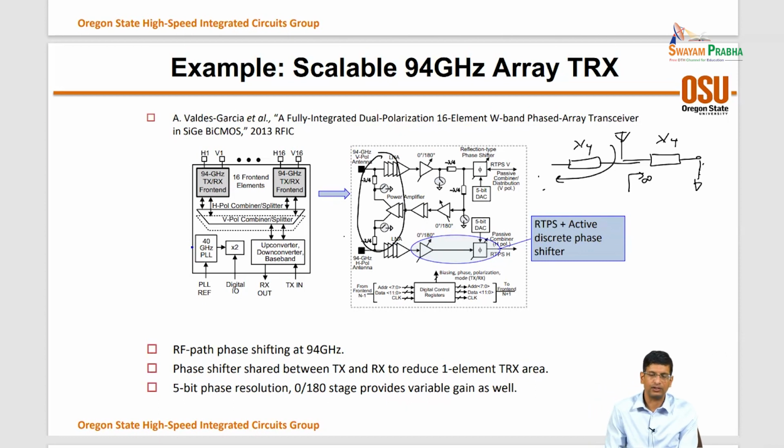And what you can actually do is start integrating some of these things inside the design itself. So in here, for example, we didn't implement 2 switches like that, but we just effectively have a short over here where when the PA is operating in receive mode, we close this switch. So this impedance over here becomes high and the signal goes through to the LNA, right?